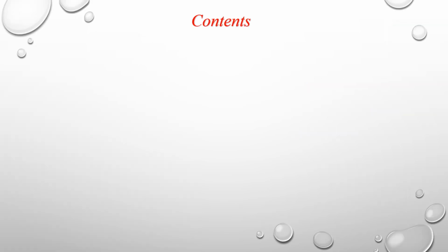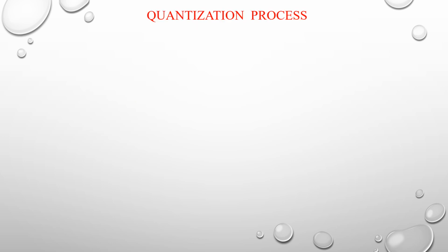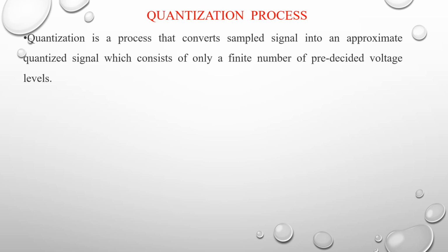In this video, we are going to discuss the quantization process, types of quantization and quantization noise. Quantization process. The quantization is a process that converts sample signals into an approximate quantized signal which consists of only a finite number of pre-decided voltage levels. In general, the quantization process converts the sample signals into a discrete signal.